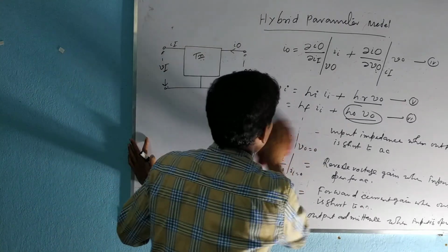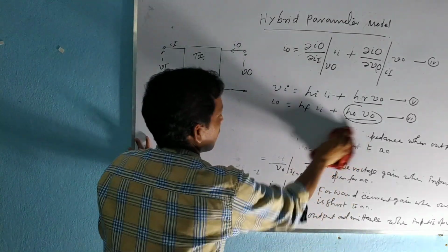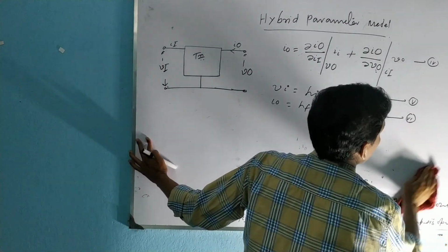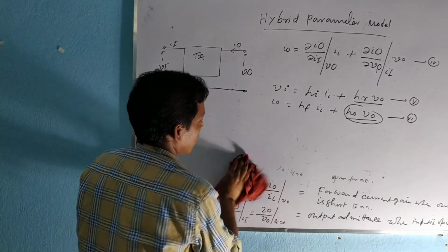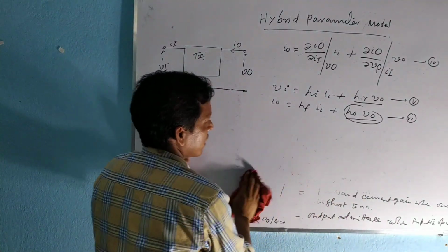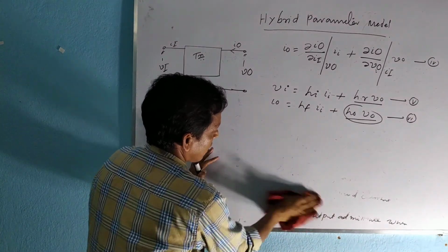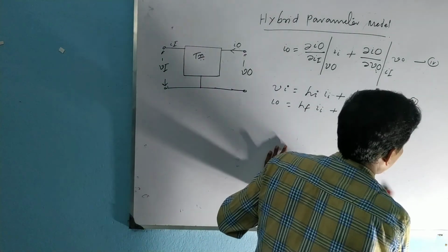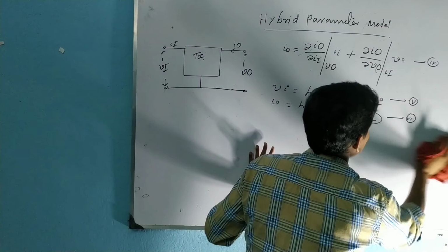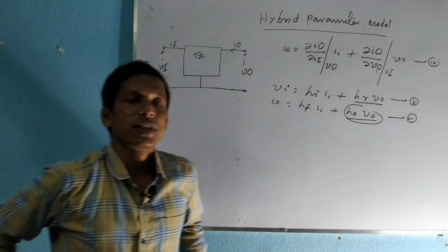And these parameters we can easily determine from the static output characteristic, and the parameters also give the real value in the audio frequency range of the AC input signal, and the manufacturer easily supplies these parameters. So the analysis of a transistor amplifier using the hybrid parameter model is very advantageous. So we always refer to the hybrid parameter model for the analysis of small signal transistor amplifiers.